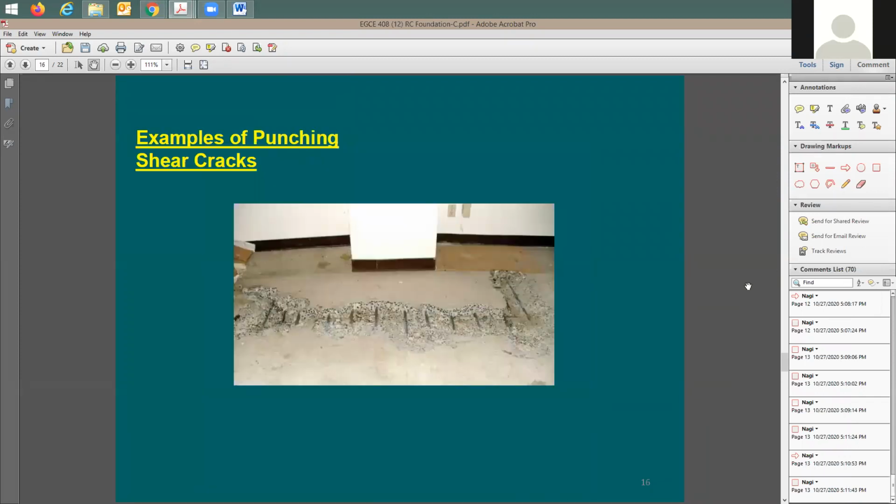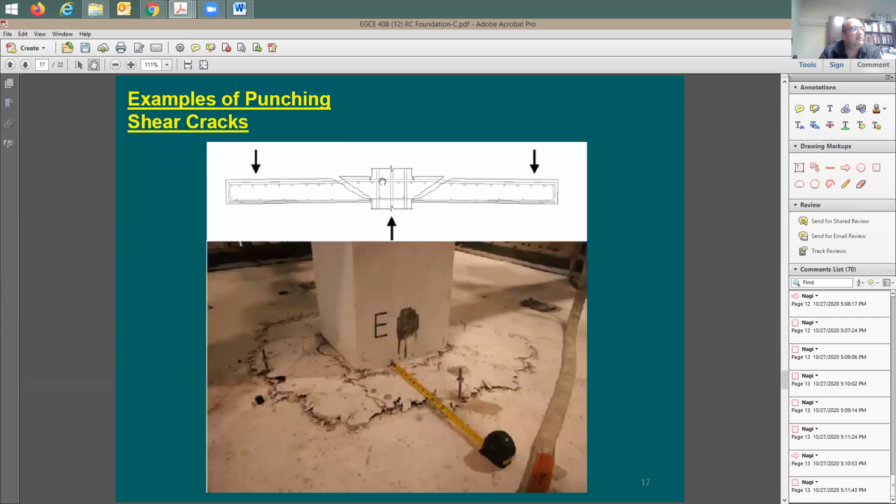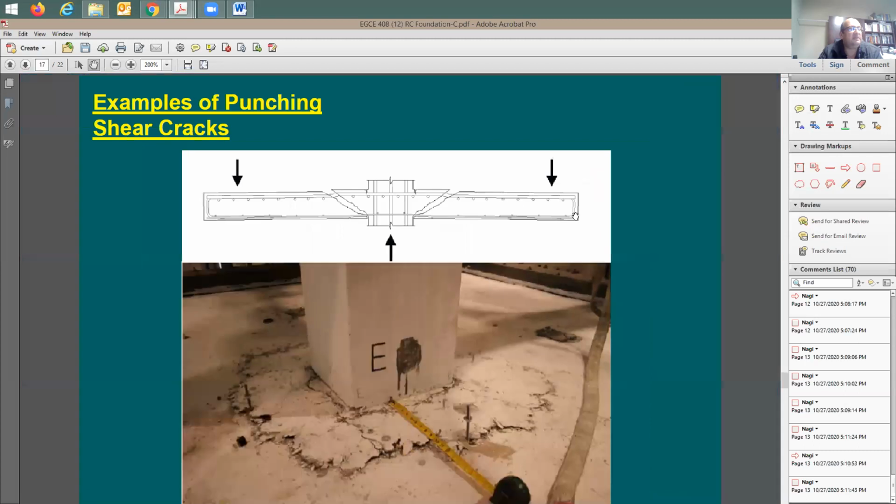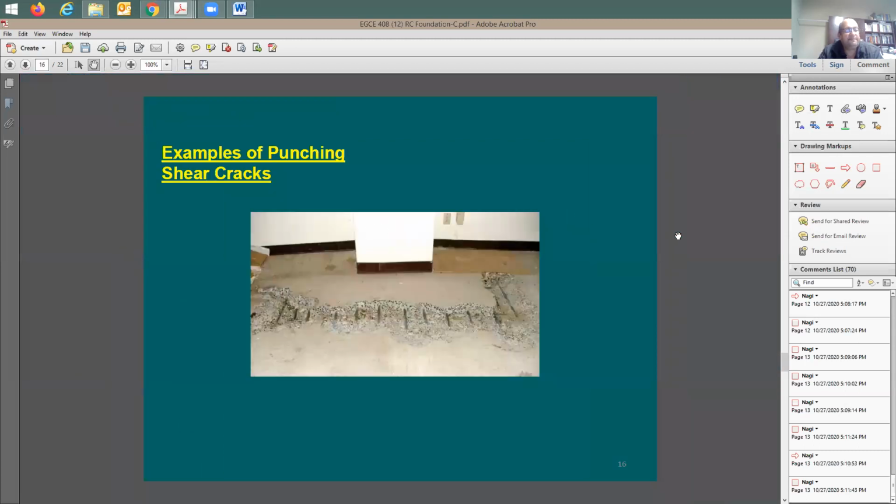So right here, it's because of the punching, but is that the reason why the rebar is being exposed? Is it also because perhaps the rebar wasn't set correctly? Because I believe you mentioned before, if we don't have the ties down correctly, the rebar can float up. It's just a slab. There's no beam. But look at this. Look what happened. Once you start to push down, you're going to have cracks like this, and the rebar is going to be exposed. So this is exactly what happened.